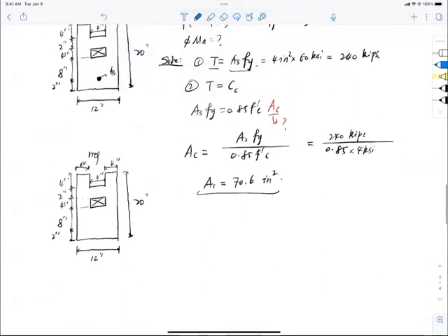I call these two little wings shaded, zone 1. If I call it zone 1 here, then I can cut another strip right underneath it and call it zone 2, can I? Now if my AC is bigger than A1 plus A2, then yes, I'm in trouble, because that means my opening is not covered, but will affect my compressive zone, right?